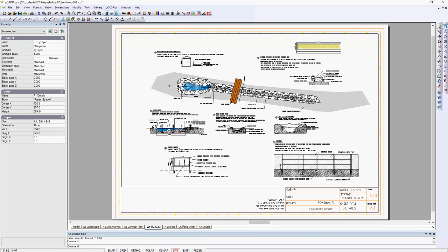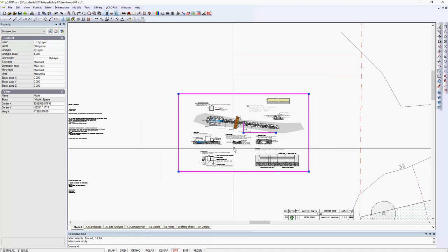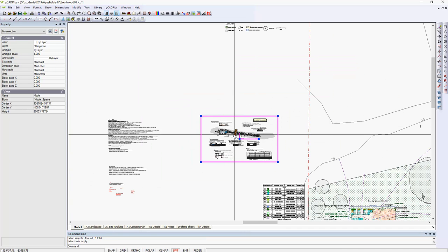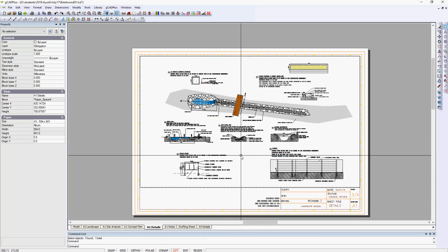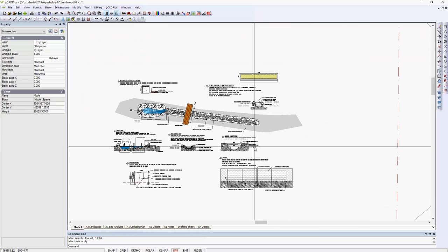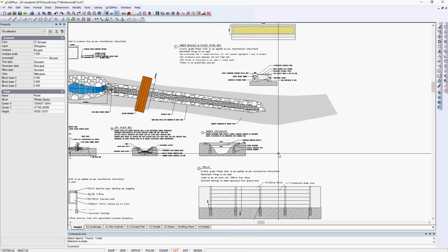Well, let's imagine that we're working on a different design and building a detail sheet. Now there are two approaches here. In this case, let me double click in here and I'll zoom out a little. Can you see that the details are arranged in model space? And I'll display on the layout, and we're looking in a floating viewport at that model space. So we could come back into the model, zoom in on that zone of details, and now we can use Insert and bring our new detail in and put it somewhere convenient. So let's try it.